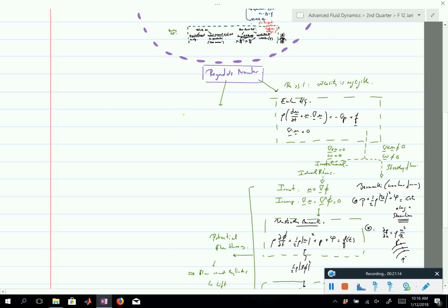So when you have unidirectional flows, flowing only in one direction, the velocity vector u is equal to, say, (u0, 0), then the inertial term just drops out of the equation. Because you're moving in one direction, you cannot accelerate and you cannot decelerate. Incompressible and unidirectional, the consequence is that essentially you cannot feel the effect of inertia.